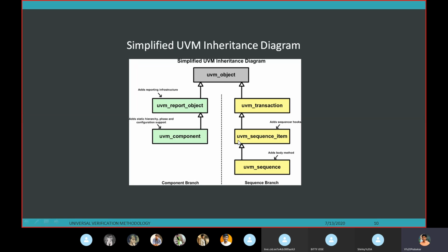Here you have to use uvm_sequence_item. So my_sequence_item extends from uvm_sequence_item, and the inbuilt methods will be available in my_sequence_item. In my_sequence_item, I can define my inputs and the control bits I have. I will declare those things, and if I want some methods, I can write those methods. Inputs and methods we write in a class, and that should be extended from this uvm_sequence_item.